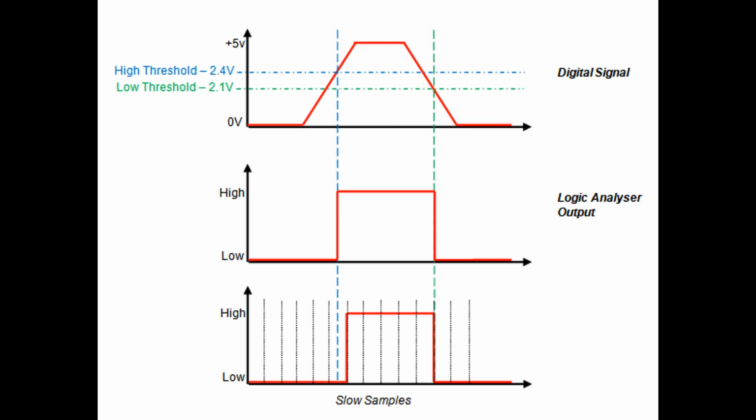So to summarize, we only use a logic analyzer on digital signals that have an acceptable digital square wave. We are not concerned with precision measurements such as rise and fall time slopes, or signal noise or capacitance in the waveform, because it will not interpret this. To look at that, we'll use an oscilloscope.